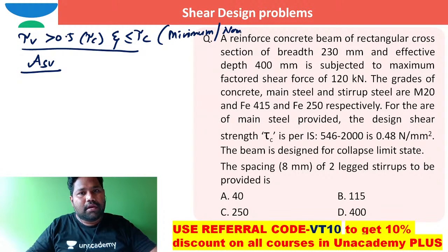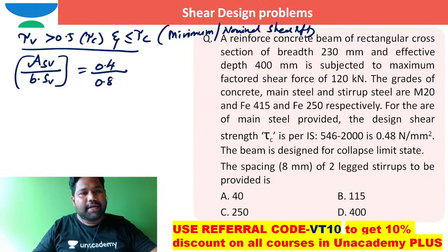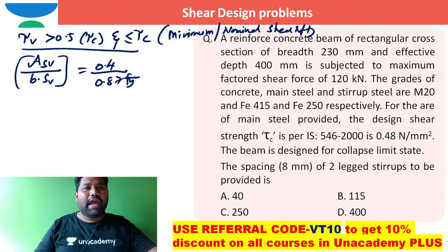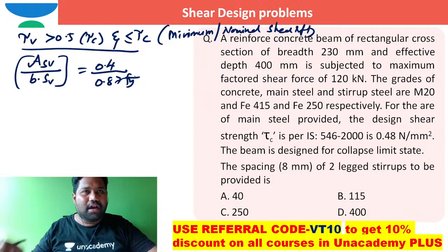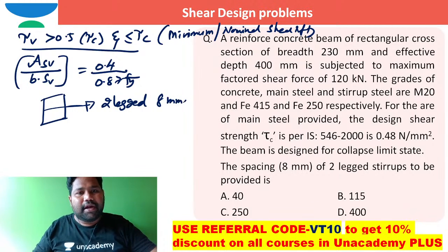Asv by b into sv is equal to 0.4 by 0.87 fy. Generally, I will fix the cross-sectional area of the vertical stirrups. If I take a vertical stirrup as two-legged, 8 millimeter diameter mild steel stirrup.